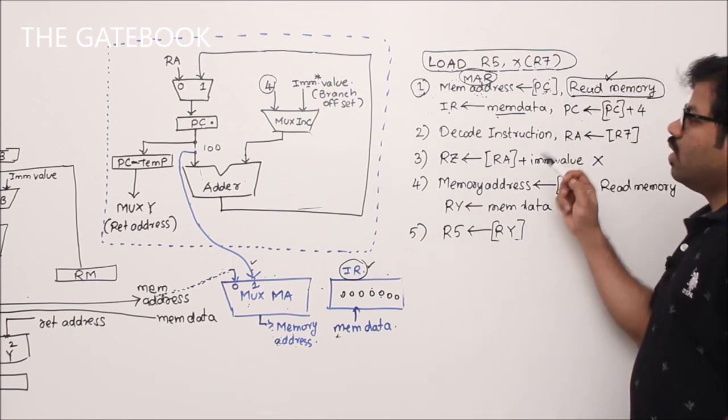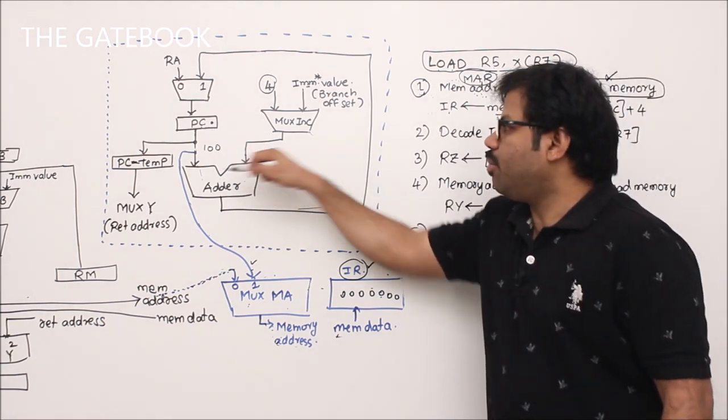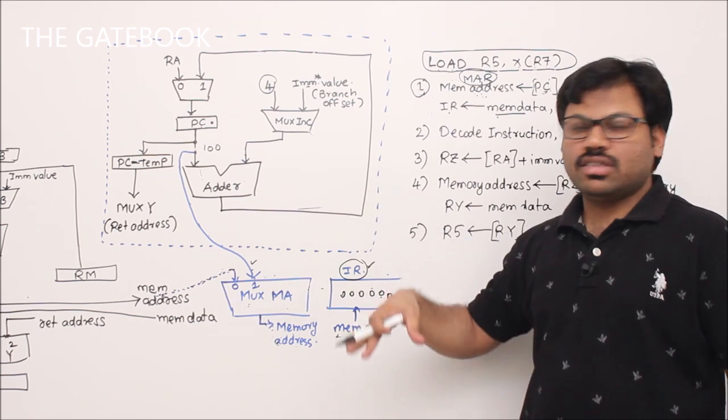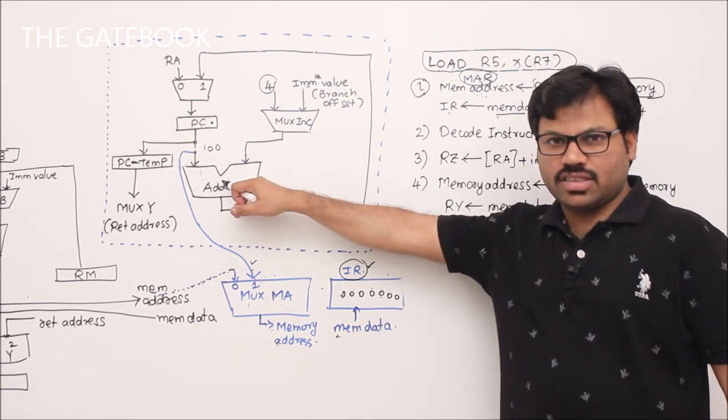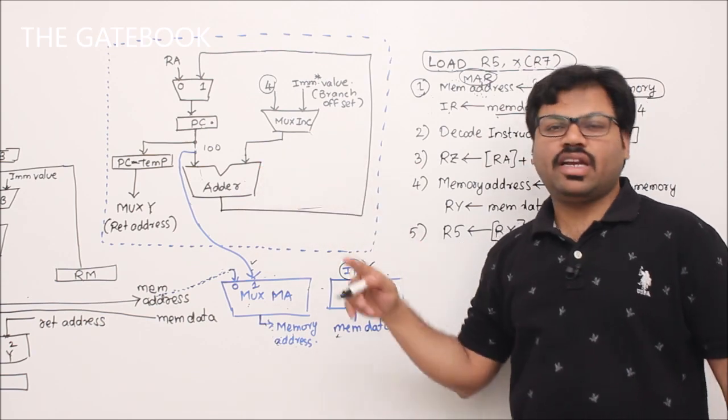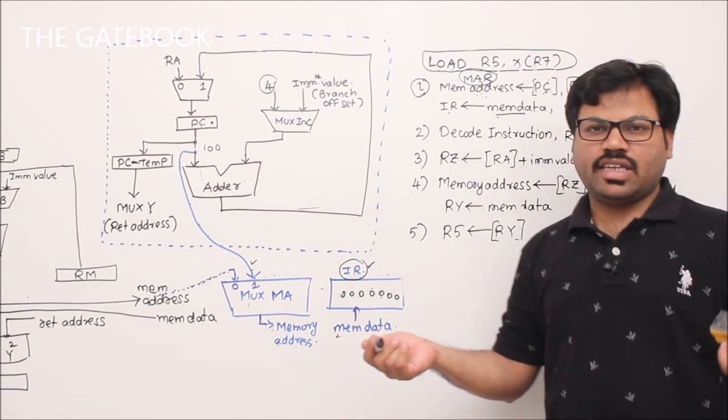Now after that, see, this program counter incrementation is not depending on all this stuff, right? This adder is not waiting for memory access, memory interface, right? So that's why the program counter will be immediately incremented. It will take very less time.